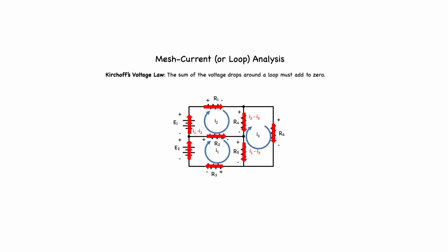Voltage drops across each resistor, whose voltages are given by Ohm's law, will carry a plus sign. Voltage rises, negatives to positives, as in the case of voltage supplies such as batteries, will be indicated as negative voltage drops and will carry a minus sign.